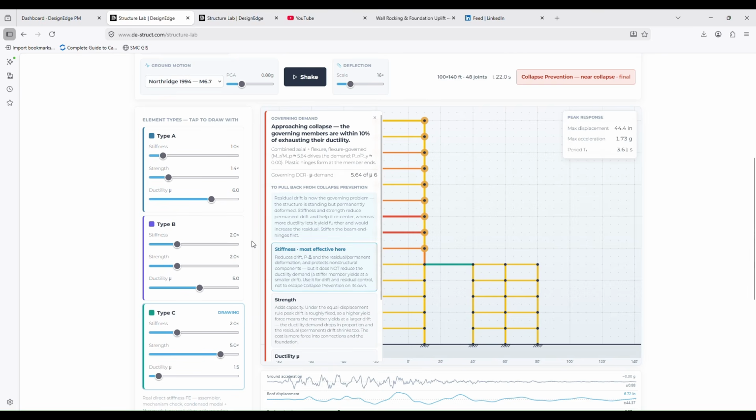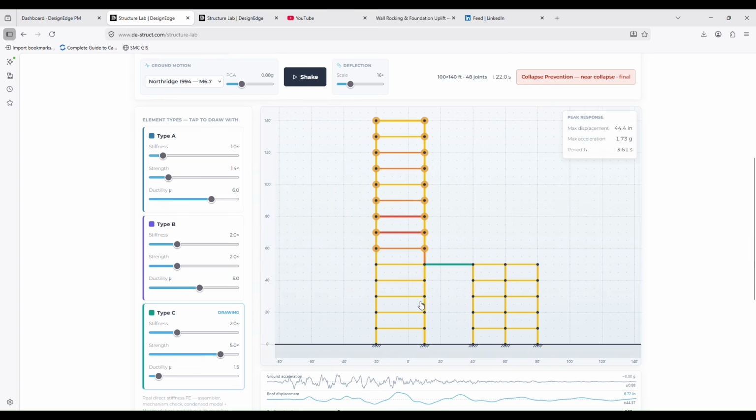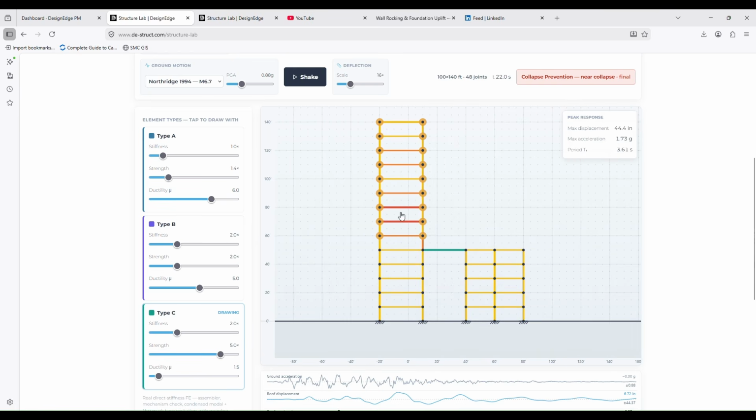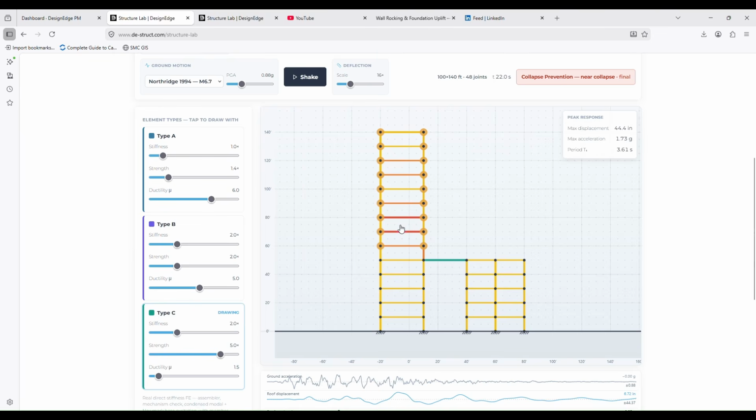So you can bring this textbook understanding into more realism and see what the actual documents, the books, the building codes actually mean by some of those provisions over here, and why we follow those provisions. And what's important to see is, right, this entire thing below the podium slab, none of that even reached life safety, none of that is orange, but then everything above the podium slab in this tower went up to orange and red, which is life safety and collapse prevention, right?